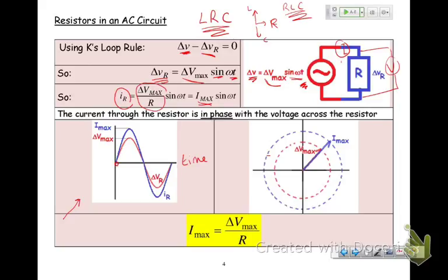That's when you turn the knob on a radio set, that's what you're playing with. You're playing with where this minimum resistance point is. And you're doing it by changing your inductance or changing your capacitance. Usually it's changing your capacitance, but you can do either one. That's where we're going. We're not there yet, but that's where we're going.